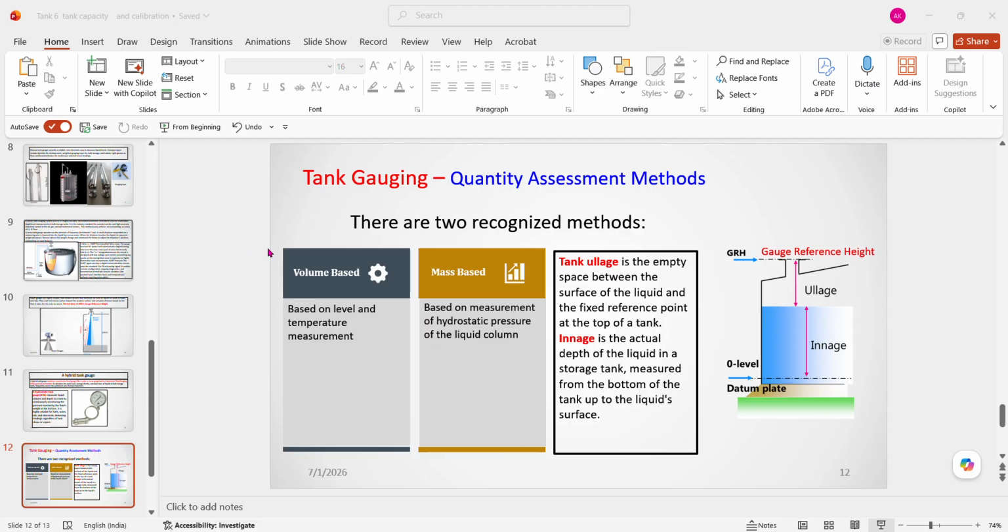So for high pressure vessels and corrosive liquids, the microwave radar method is very important for accurate measurement of the level. Servo uses a small displacer suspended by a wire and a motor. A small displacer, like a ball, is tied to a wire and run by the motor to physically track the liquid surface. Where is the liquid surface?